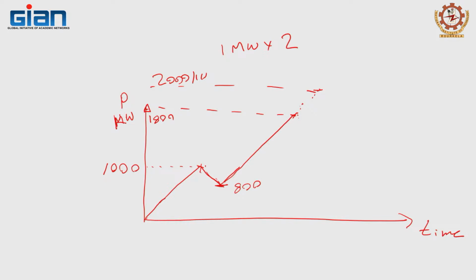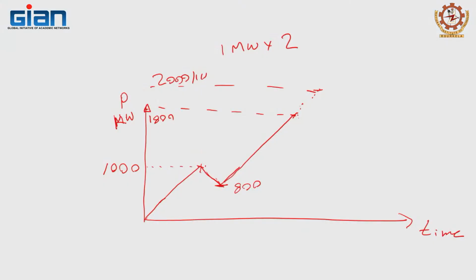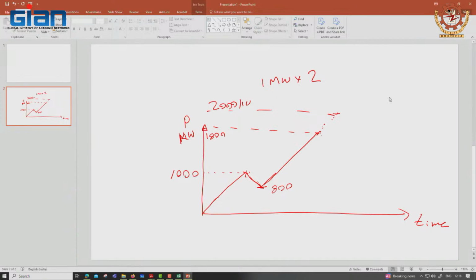Now, when the water level goes down, how do you stop machines? How do you keep the machines at the best operation point? That depends upon the efficiency curve. So, we will try to keep the machines at the better efficiency points in the operation of the power plant. All these things will enhance the total power generation. So you have to think about this when you have multiple turbines, how your plant generates electricity.